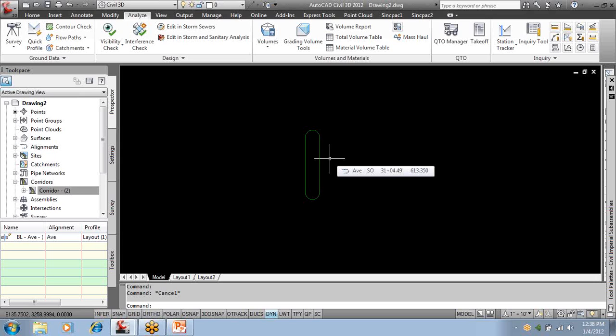So if I ran my alignment around the perimeter with curbing, and then the islands in the middle, I would have to define my pavement grade, and then have that line copied up 6 inches above it to define my actual curb height, correct?